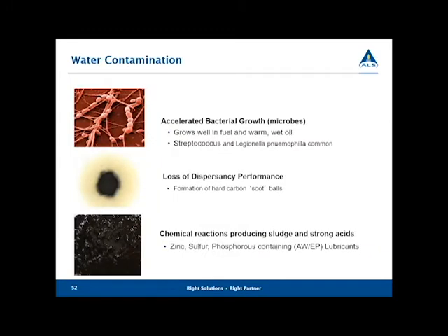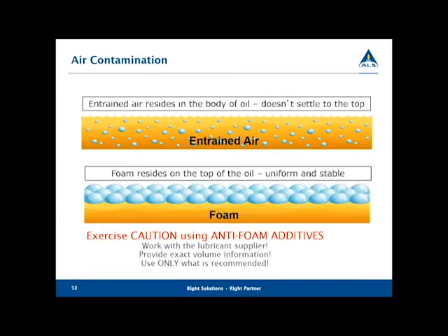Always remember that. Also, water can contribute to biological growth and loss of dispersancy, especially in engine oils. It also contributes to chemical reactions, producing sludge and strong acids. It reacts with the anti-wear and even extreme pressure agents within the lubricants. Remember, these things are polar active. Water is polar, as are a lot of these surface active agents, as well as the molecules found within the oil to do its job. These things are polar active, and they're going to compete with water, and they're going to react with each other.